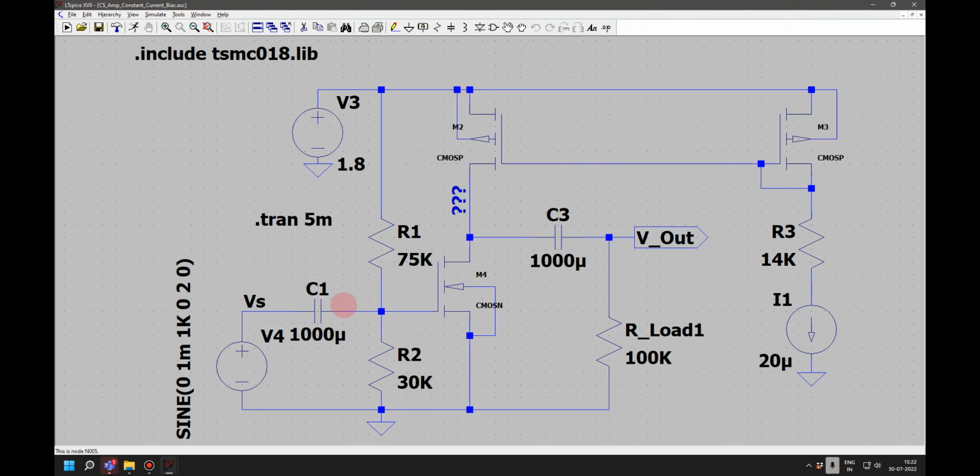So one more thing, we have not talked about this output voltage swing here, right? To keep the transistor in the saturation region, V out is limited, there is a max V out. We designed it that way, right? We have kept it somewhere in between here. If you keep increasing Vs, after some time it will touch the saturation levels.